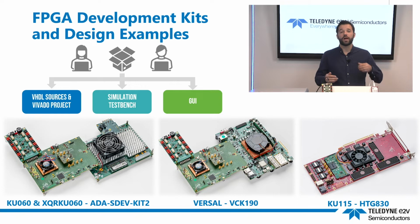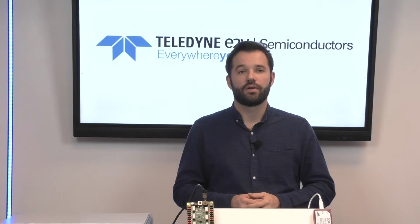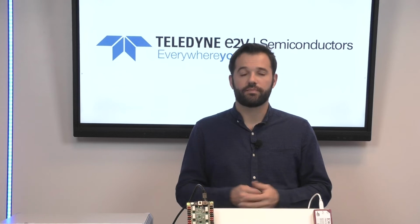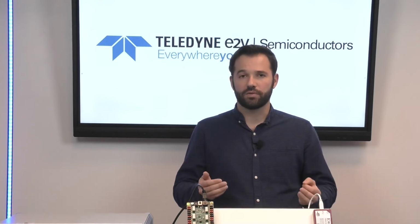In this video, I will give you all the information you need to get started with the EV12DD700-FMC Plus board and your FPGA using the evaluation kit from Alpha Data embedding a Kintex UltraScale KU060. First, we will see all the steps to create Vivado project, generate the bitstream and load it in the FPGA. Then, using the graphical user interface, I will demonstrate how to generate a signal in Ka-band.